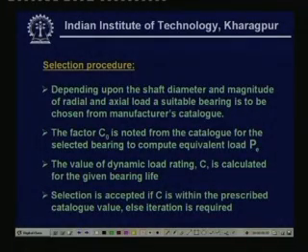So, you choose a typical bearing, say a single row deep groove ball bearing, and in that particular catalog you find what the bore size of the bearing should be, so that it fits onto the shaft diameter. Then, for that particular bore diameter you will get all the dimensions of the bearing and also two factors: one is the C0 factor, and another is the C factor. Once you get the C0 factor, you go back to the chart to find X and Y, and subsequently you can compute the equivalent load Pe.